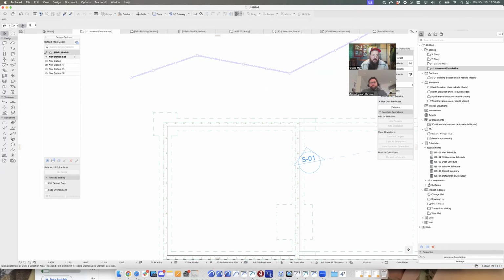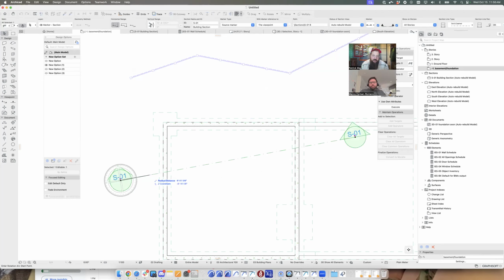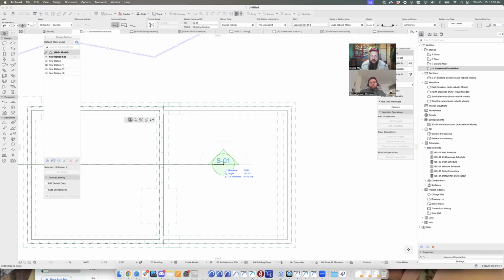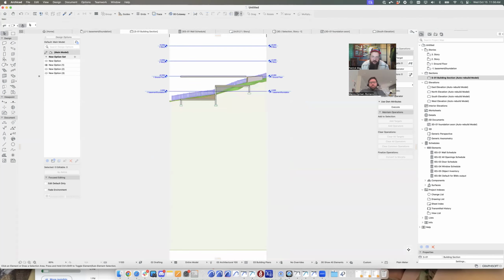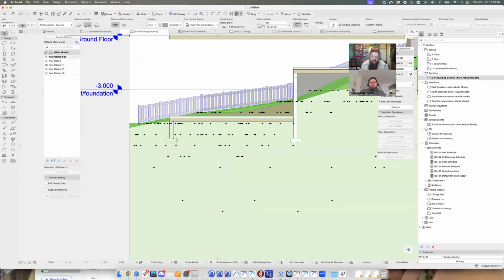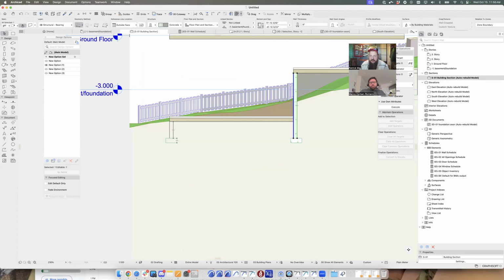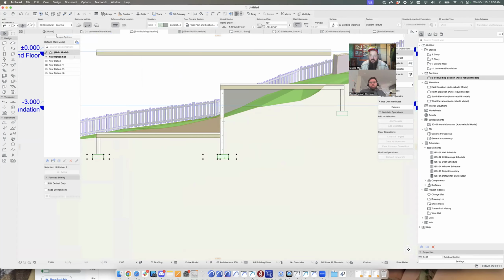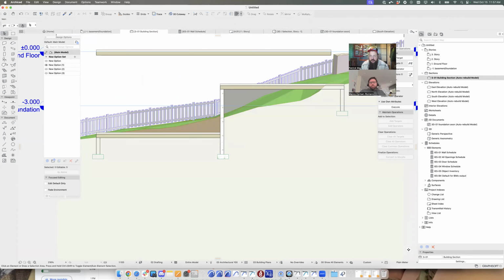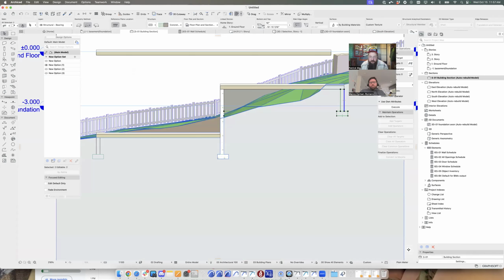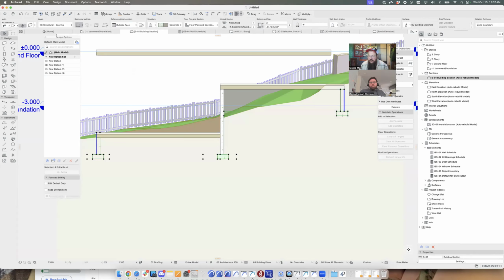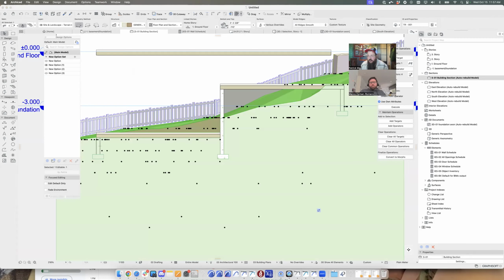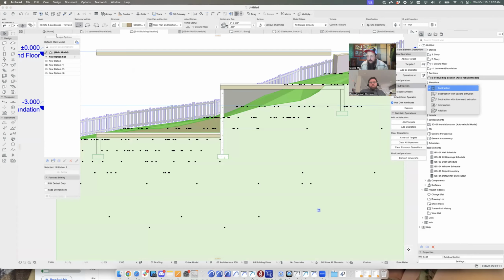The other thing is, bear in mind that just because I have that site cut out by my main floor, if I open this back up, it's not necessarily going to play nice with these walls, right? Because the mesh and the slabs and the walls don't automatically interact by building materials. So you'll still need to grab your walls and your slabs and set those as operators, set your mesh as a target, and a basic extrusion or subtraction.